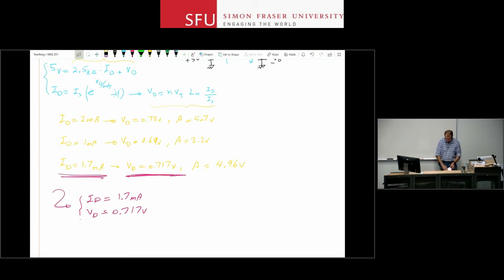And you have examples in your textbook, in your slides on how to go through some examples, and then you can actually go through them and exercise. So for example, the next slide is a circuit with two diodes in parallel, but one of the diodes is significantly larger than the other one. How do you calculate ID for each one of those two cases? And if you're solving that circuit, note that ID for the two diodes will be different because ISs are different, but they have the same VD. And that should help you write the KVLs relatively easily and solve that circuit.